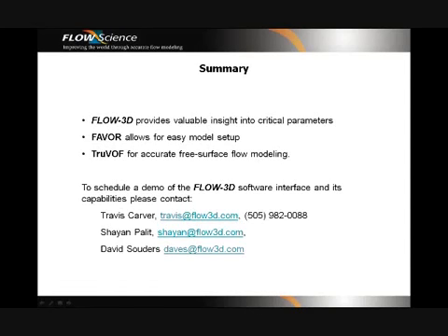And let's see, here's another question. How do you specify the flow rate directly to a given boundary? Flow3D now has a volumetric flow rate boundary condition where you specify the volumetric rate and the vector components to set the direction of the flow. And then one other point to add is that you can set a free surface at the boundary to control the flow elevation entering.